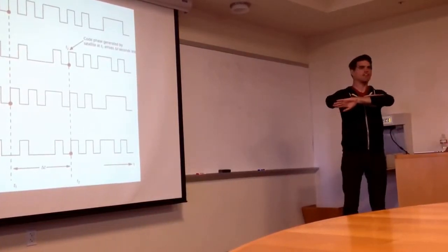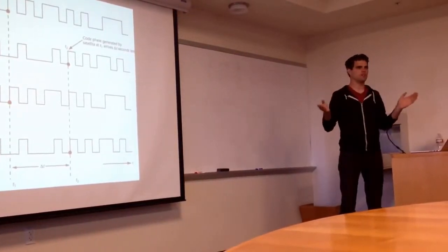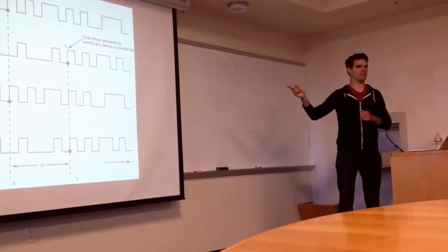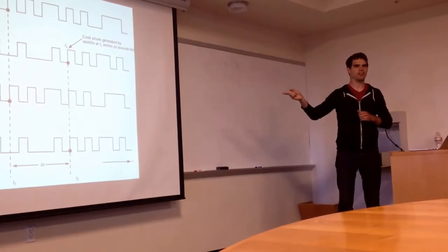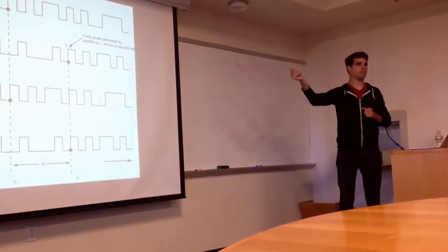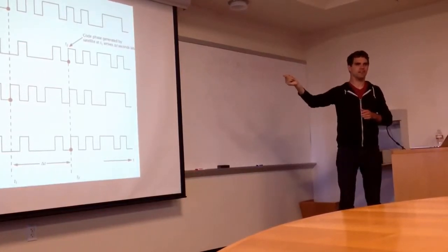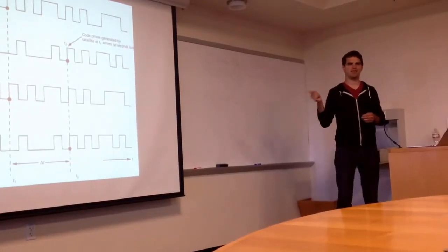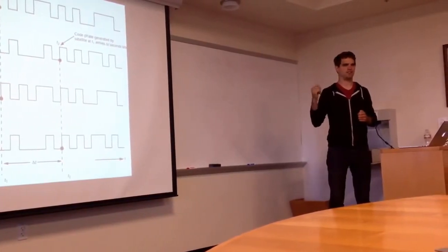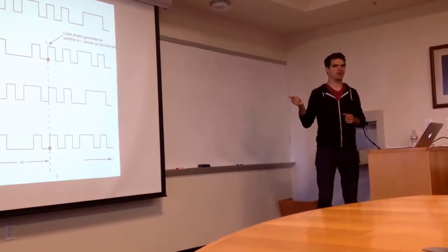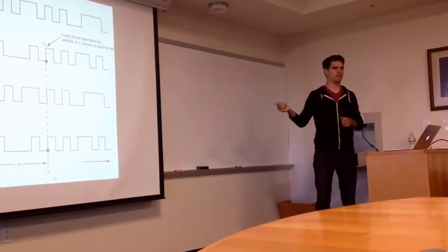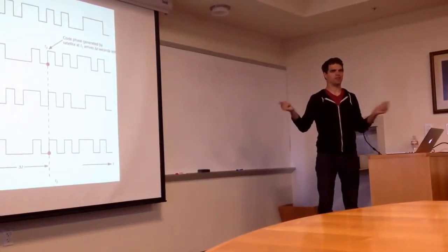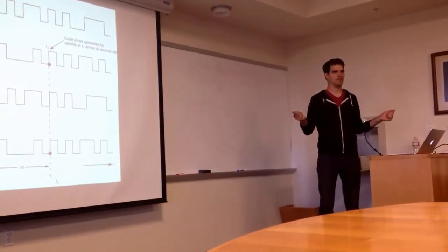amplify my signals. The other thing you can do is, if you put 32 satellites on the same frequency, that's okay. They all use a different string to encode their data with. And so if I'm receiving a different satellite, it just looks like noise to me. What's kind of cute is that this is exactly the same technology that spy agencies use, because if you don't know that 1023-bit sequence, then how are you going to decode the data? It just looks like noise.